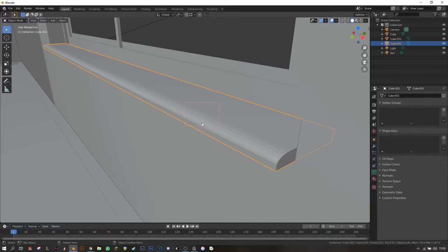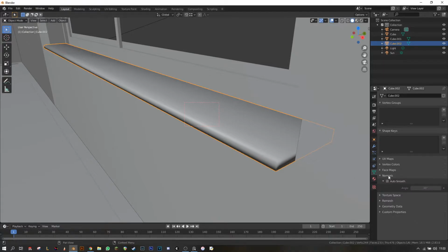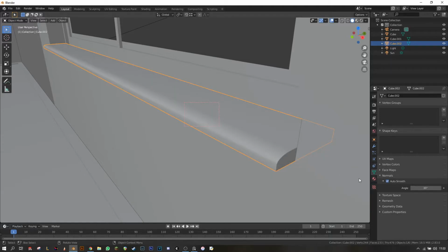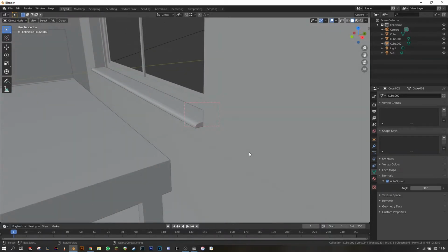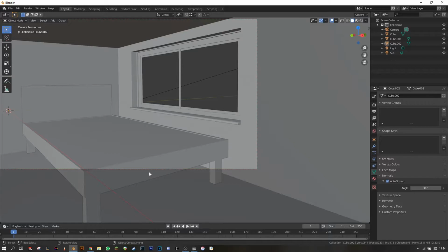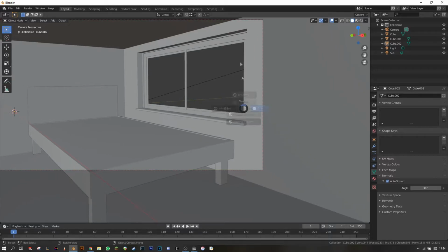And now you see it's lots of separate faces, which doesn't look very good. So the way that we're going to fix that is right click and click shade smooth, but now we've got those strange shading on the side. So to fix that, we're going to go over here into normals on the little vertex panel and just select auto smooth. So what that'll do is any angle between two faces that's 30 degrees or less, it's going to smooth over, and any that are greater than 30 degrees, so say these ones are 90 degrees, it's going to make them nice and sharp. So it just fixes it all for you. It saves you a lot of time and effort. You used to have to select each face around it and select just the ones you wanted smooth, but it's a lot easier now. So that's looking better.